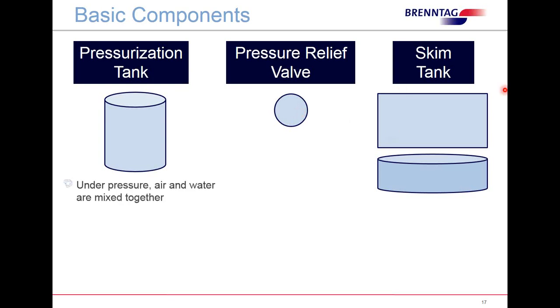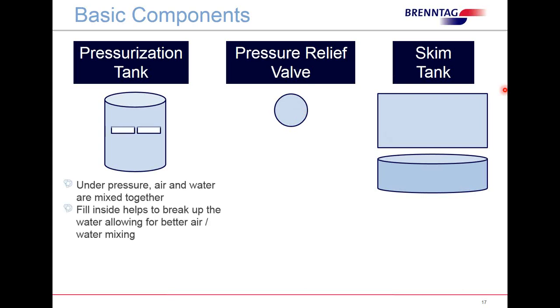The pressurization tank is a tank where water and air are mixed together under pressure. Usually there's fill inside of the pressurization tanks that allows for the air and water to mix better. Very similar to the fill in a cooling tower, where the water hits the fill, breaks into smaller particle droplets, allows for better evaporation, thereby a better heat transfer or loss of heat through evaporation. The fill in the pressurization tanks is basically the same.